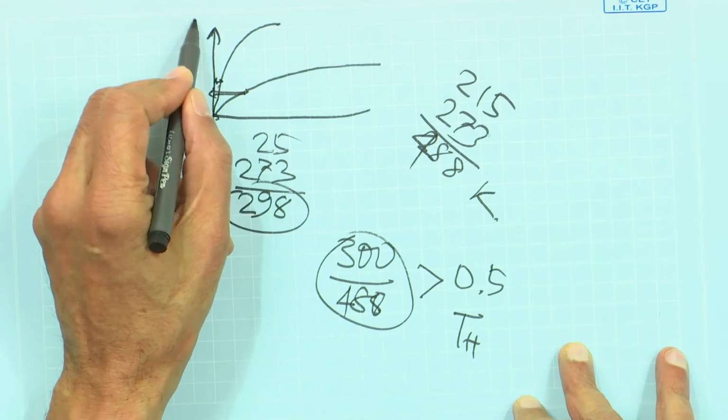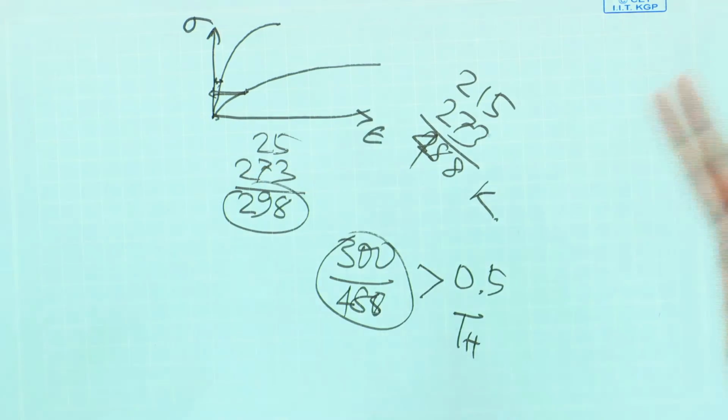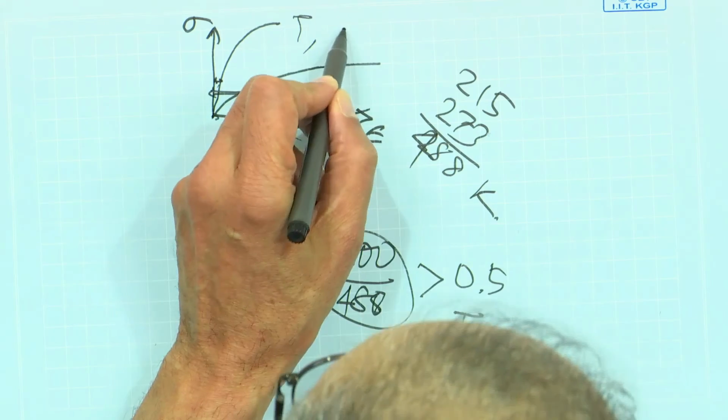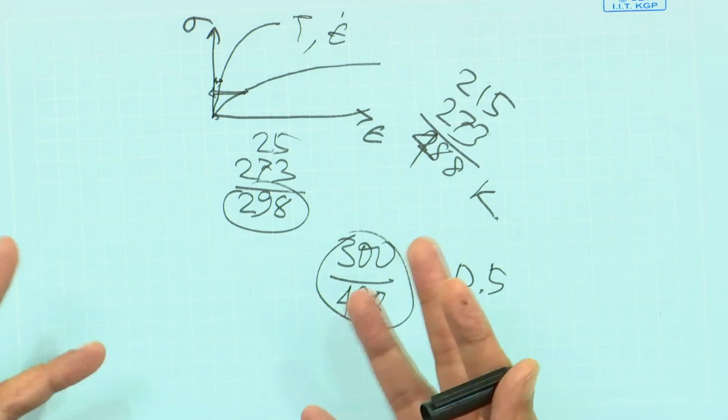So if that is stress and that is strain, which one do you call the stress strain curve? Well, it depends on the temperature, the loading rate, environmental conditions, the grain microstructure, and a lot of other things. That's why Professor Ramanujan very correctly pointed out there are complex materials for which it's meaningless to talk about just one stress strain curve. It depends on the loading condition.